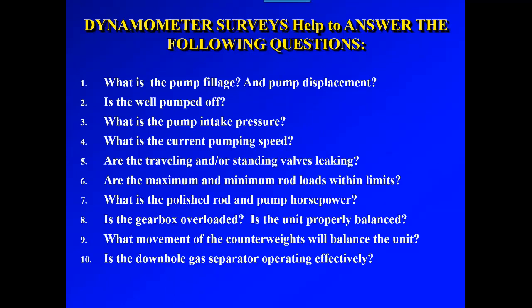There are some basic questions that we can answer by running this particular test. First and foremost, what is my pump fillage? Am I pumping the well off? How can I optimize? There are different things, pump fillage being a big portion of that. And what is my pump displacement? With a dynamometer card, we ultimately calculate the displacement. Is what's going into the stock tanks, the production tanks, and what I'm measuring with the dynamometer adding up? That's an important point.